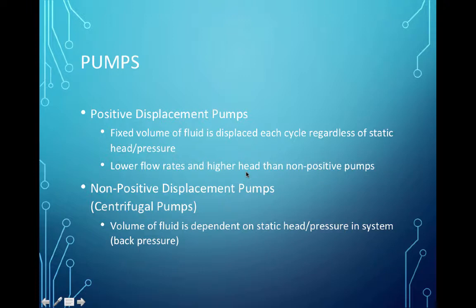There are two general categories of pumps mechanically. One is positive displacement, and the other is rotating or non-positive displacement or centrifugal. In positive displacement pumps, a fixed volume of fluid is displaced or moved every cycle, pretty much regardless of the static head or pressure. These kind of pumps don't produce very much flow rate, but they can produce pretty enormous heads.